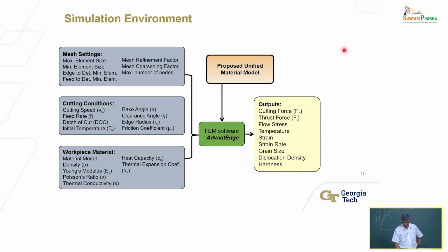You can implement this in a finite element model to solve these. The problem of deformation during cutting is not simple. So far I only covered how to describe the material behavior. I'll talk about friction as well, but you also have to be able to simulate the material separation, the fact that as the tool goes through the material, you're cutting and separating it.